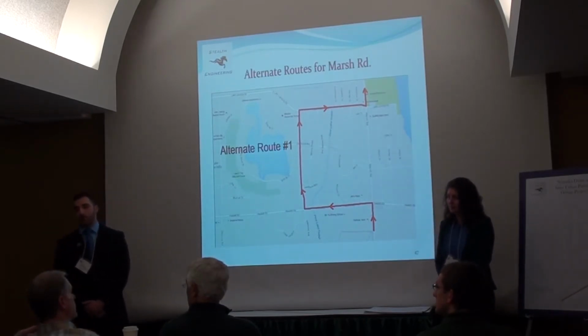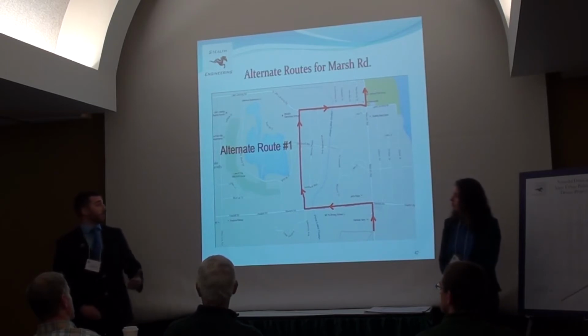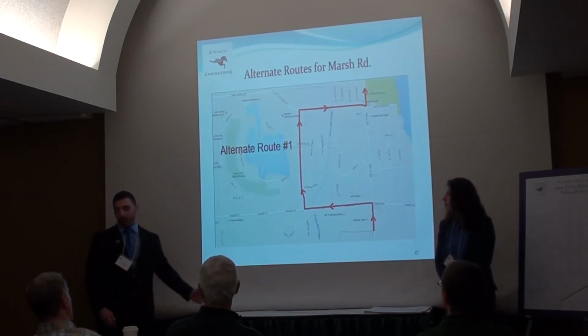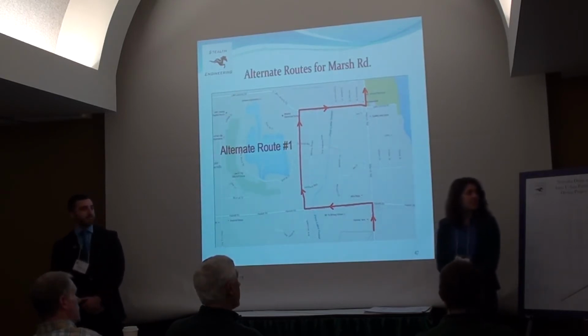Okay. Could I just jump in on that for a second? If the residents might not like the swales, maybe there's not room by the house, why not just capture and enclose everything? Well, we wanted to consider sustainable and green design. We saw that as having these swales, maybe with some greenery, you could kind of spice up. A storm sewer could also be designed in the same locations and serve the same function. We just figured the more sustainable, the better.